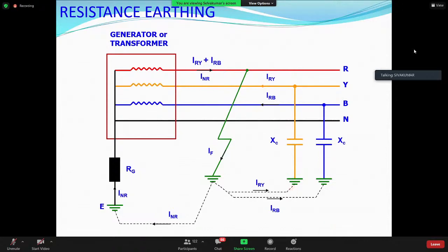Now, since the core material is involved in carrying the current during an earth fault inside a rotating electrical machine, the core material itself is a high resistance material. It is not copper or aluminum, it is iron. And because it is made up of lamination, thickness is lesser, resistance is more. So by material characteristic, resistivity is more. By material construction, resistance is more. Huge heat will be produced in the core of the machine. When the earth fault happens, huge heat will be produced in the core, and the core insulations will melt and the core will become a single mold.